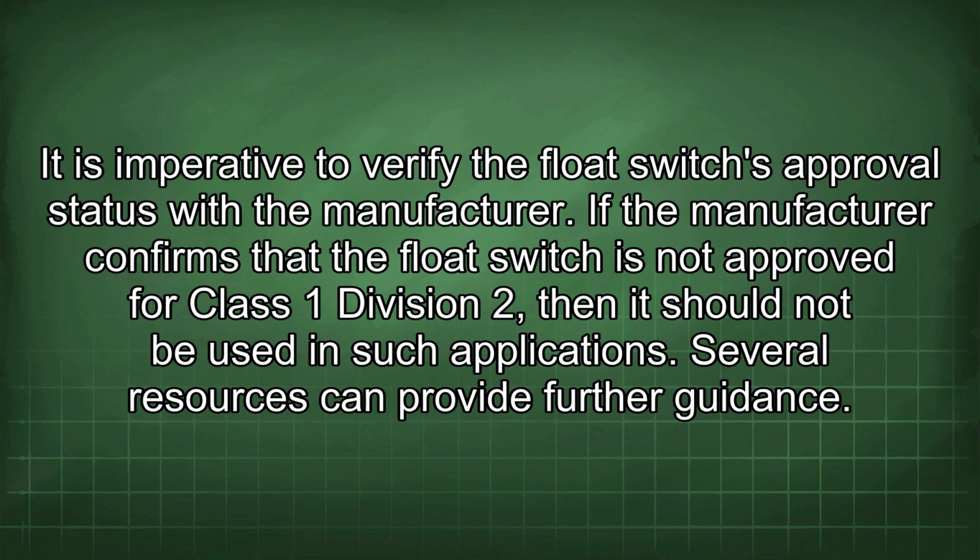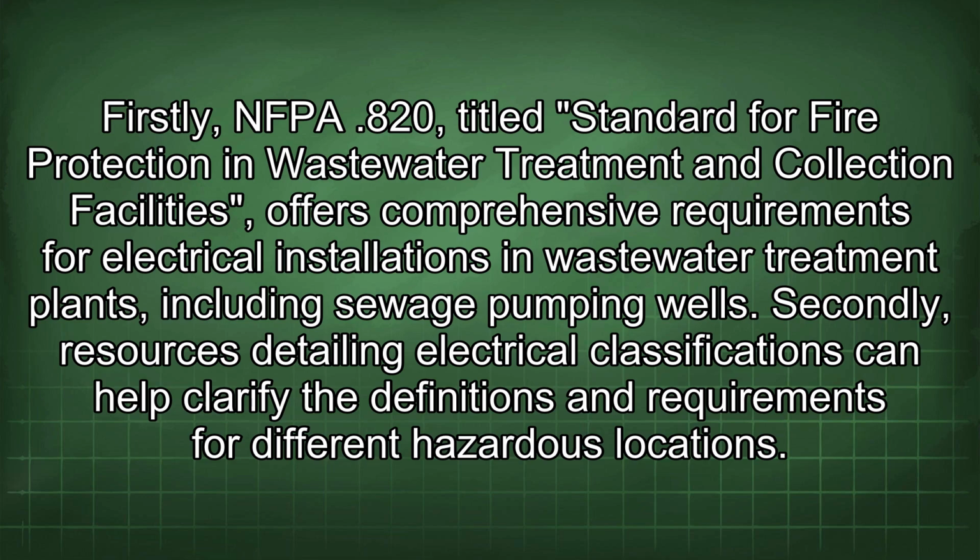It is imperative to verify the float switch's approval status with the manufacturer. If the manufacturer confirms that the float switch is not approved for Class 1 Division 2, then it should not be used in such applications. Several resources can provide further guidance. Firstly, NFPA 820, titled Standard for Fire Protection in Wastewater Treatment and Collection Facilities, offers comprehensive requirements for electrical installations in wastewater treatment plants, including sewage pumping wells.